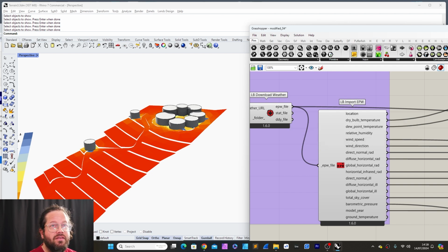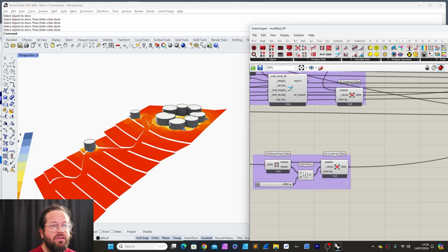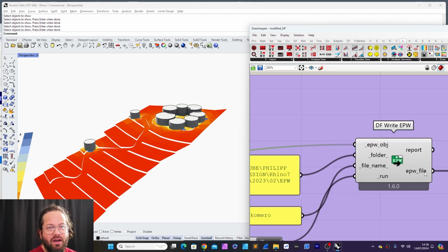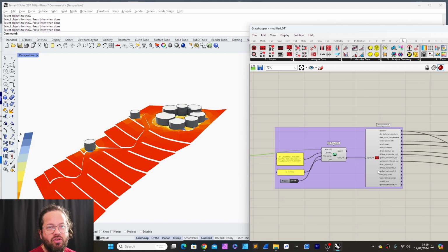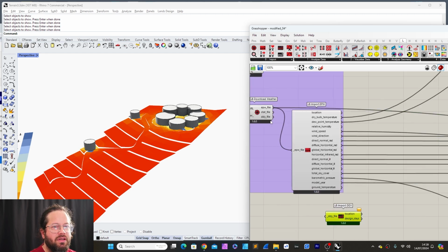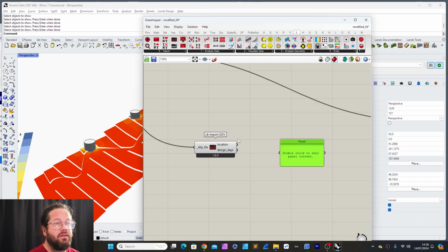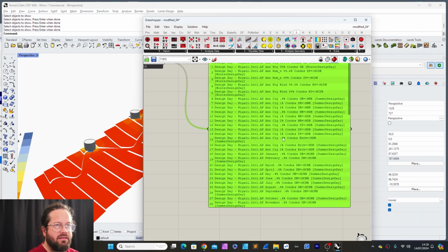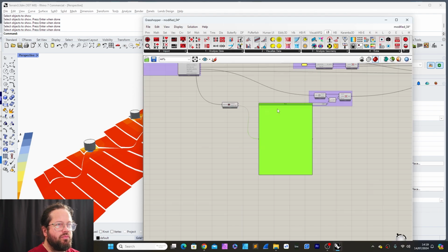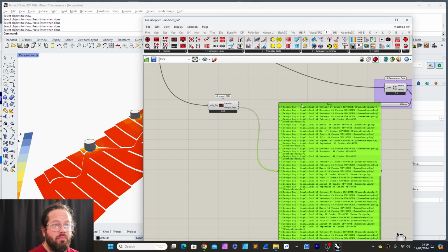There's also a statistic file in here in the weather data. We could produce that. We could actually create a modified version of it. I will not show that now, but I want to show that you could check here, for example. Let's look at design days. I mean, we looked at this before, but design days, what's in here? So in here, the design days which you can use, which have a certain property. So that's one way to understand a bit more about your site.